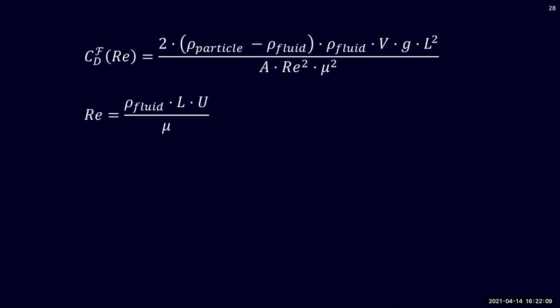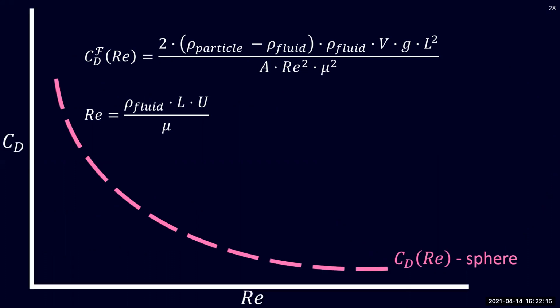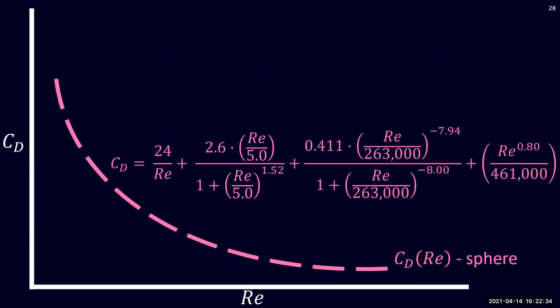So now we know that Reynolds number and drag coefficient are the dimensionless numbers that need to be matched. For a sphere, and other simple geometric shapes, there are data that have been gathered from sinking spheres and plotting out data points. Curves have been generated, and from those curves there are known equations.